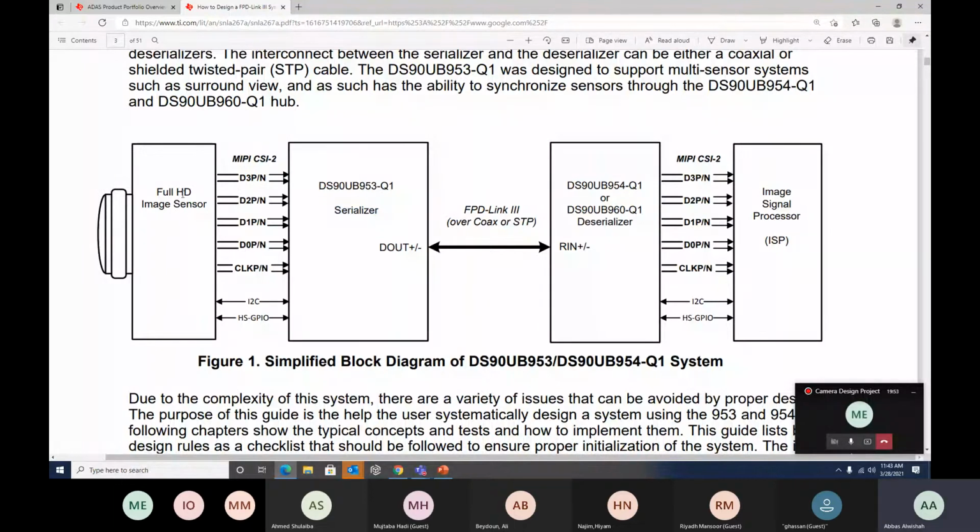So you could have a very high resolution imager here, and the serializer needs to match with it, because the imager could be sending data over 10 gigabits, and the serializer could be only processing at least this family up to 5. So we need to go to the next family higher.